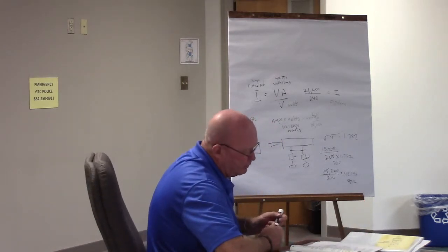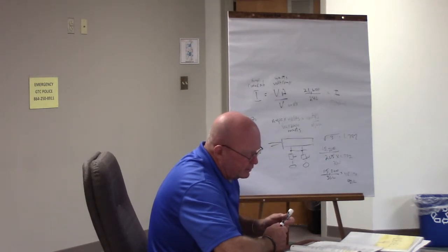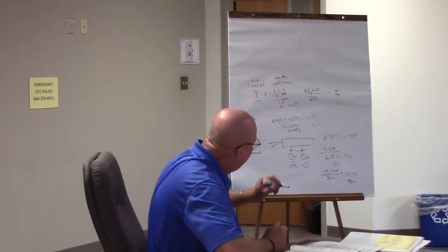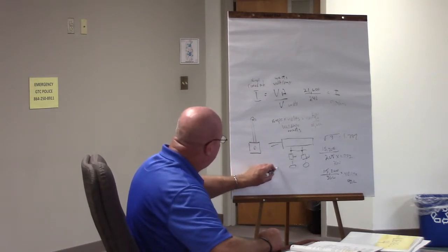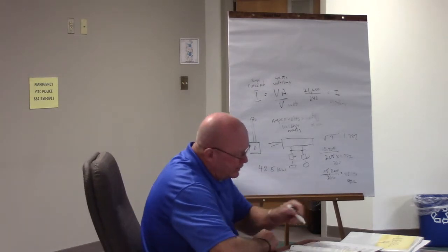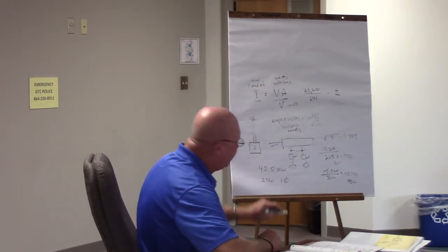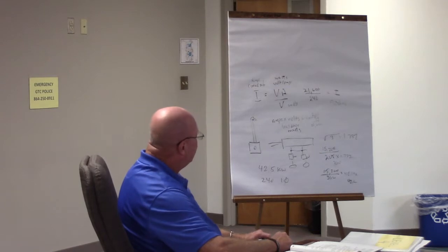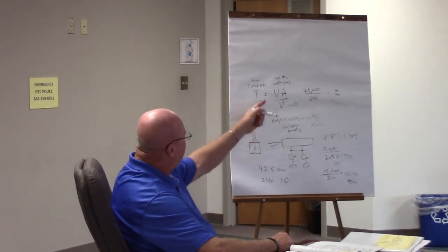If you look at example number 1, it says, what's the ampacity of a single phase resistance load with a nameplate 42.5 kW. Now they give us kW. Okay, and it says it's 240 volt. That's one of the things we know, and we know that it's single phase, don't we? That's what we know. So what do we have to do now, guys?